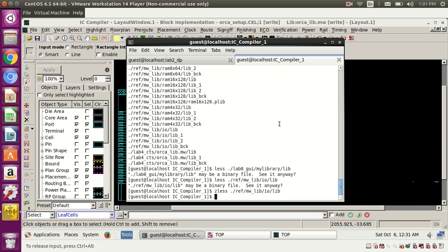Suppose we have a mux. For the mux we have given some input enable, and the enable signal is coming from something, and that mux output is going to some different flops. So the mux is a 2 by 1 mux, and the select line is always 0, and that 0 is always set, case analysis is there, or the data is stable for some time.